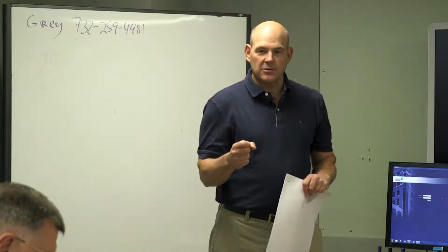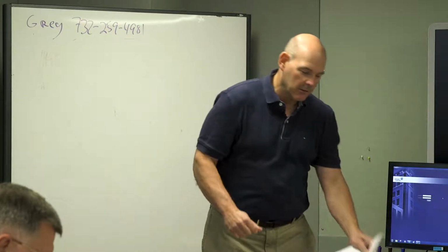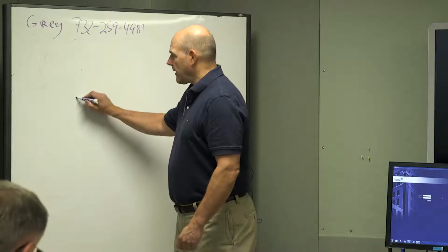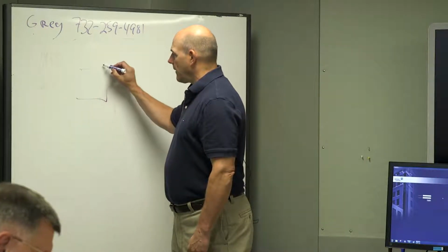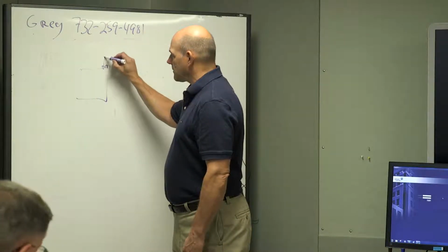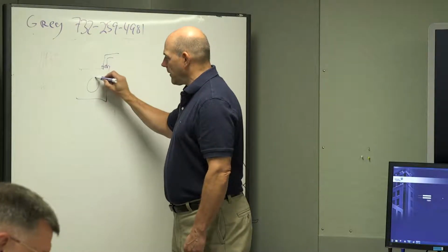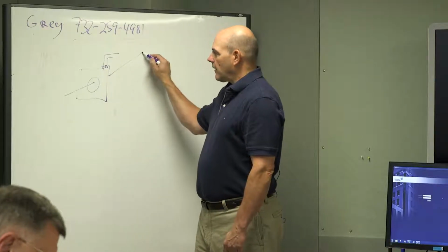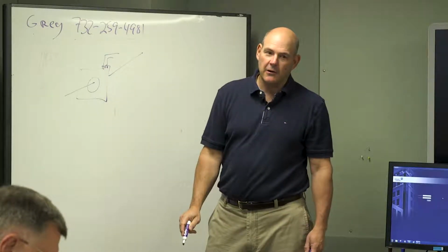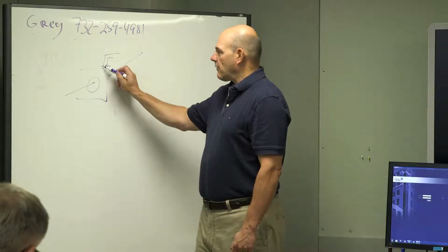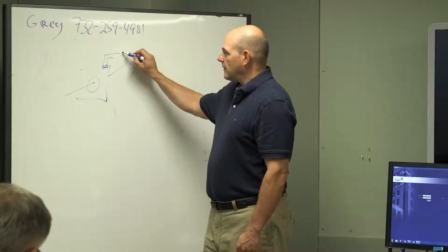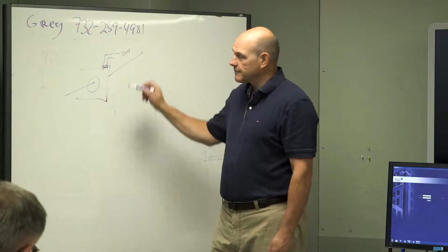The S stands for status. That tells you there's a current donut. It's a round device that looks like this. Let's see, rectangular. Okay, and it has a place for 2 wires to come in here. It has a hole in it. And what happens is the wire goes through here and creates a current. And when it creates a current, it closes this contact. And that contact tells us the pump is on or off.